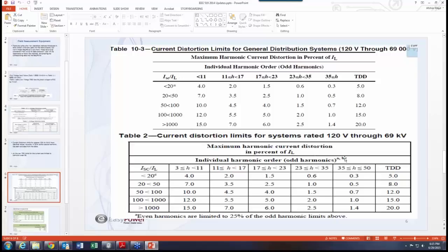You go to the upper end of this frequency and you will see it says harmonics higher than 35. Higher than 35, the question would be how high you really want to go. And I think it's a more scientific, more realistic engineering definition that it cuts off at 50th order. You go from 35 to 50th and that's it. You see the difference here, even though the limits haven't changed. They are exactly the same limits if you just look at them here. The second harmonic was excluded, which is important.